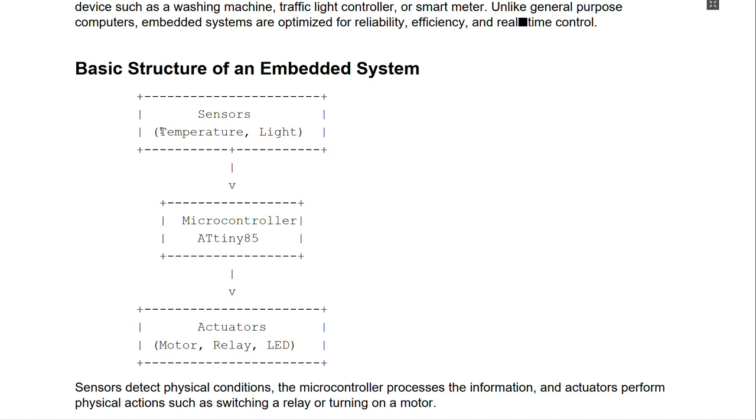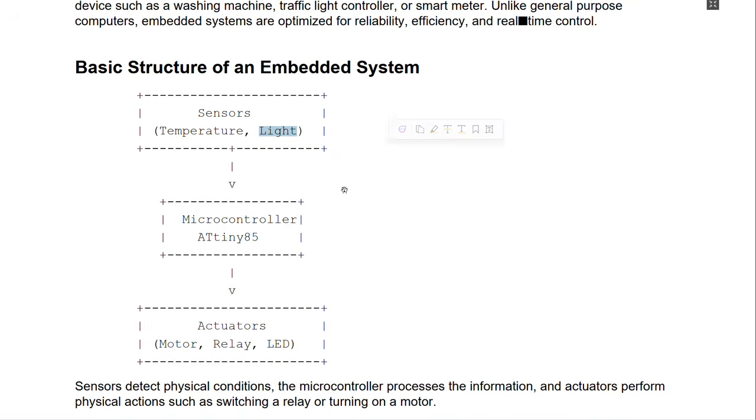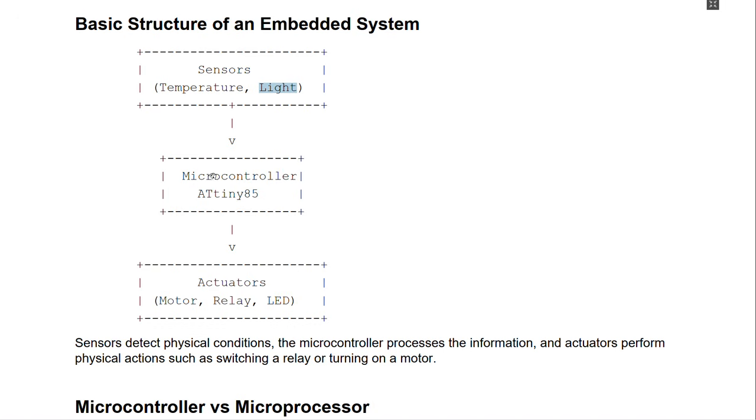Let's say a homestead is operating at 240 volts. That's the voltage sensor giving us information. And the current at the moment is saying 18 amps or 10 amps or 5 amps, or someone is cooking, right? So the meter multiplies that and the number of hours you've been using that power, because voltage times current is power, in volt-amps or watts, depending on the kind of load you have.